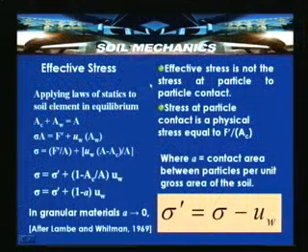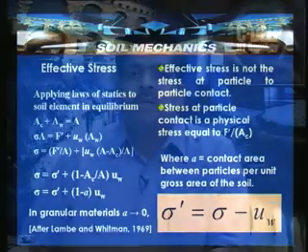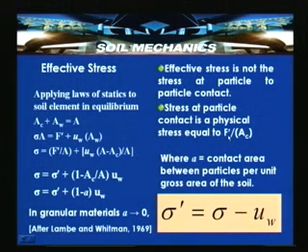If you look at this slide further, the effective stress is not the stress at particle to particle contact. That is required to be noted. It is acting over an imaginary area A, passing through pore water as well as through solids and some contact points. The stress at particle contact is a physical stress equal to F dash by AC. It will be very high, because sometimes minute contact areas can induce very high contact stresses.